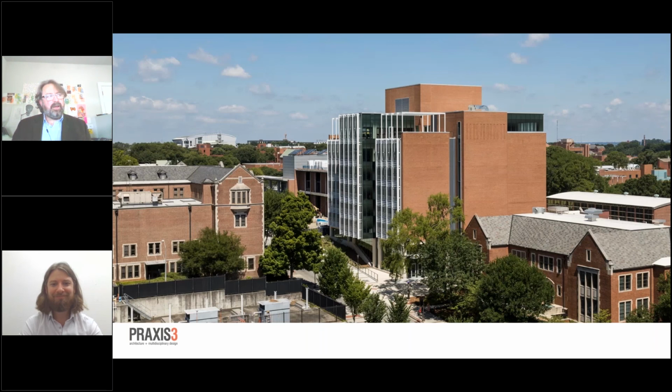And then at the Georgia Tech Library, because we looked at those diagrams where we were tearing off the brick on the north and south facades, we did salvage all that brick for reuse, because you need lots of brick to finish out all of these edges where we're inserting new windows, and there's always point up and repair and things that have to be done. Using the existing brick to match the existing brick is always a better option, architecturally speaking.